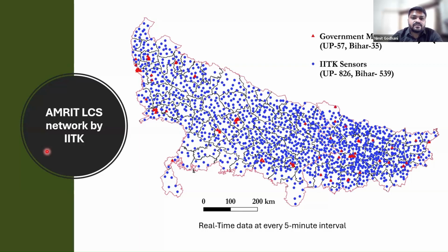In the reference grade monitor, we are now using EBAM, which works on the attenuation principle. When the humidity increases to more than 80, 85 or 90 percent, just before the monsoon or rainy season, it shows negative results, or lower concentration than the actual concentration.